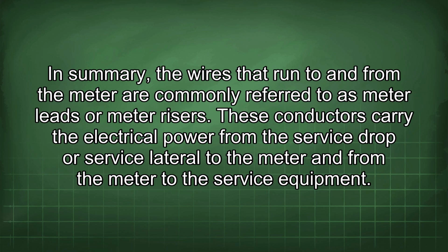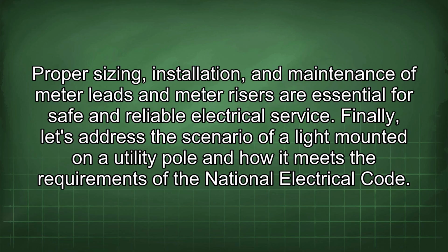In summary, the wires that run to and from the meter are commonly referred to as meter leads or meter risers. These conductors carry the electrical power from the service drop or service lateral to the meter and from the meter to the service equipment. Proper sizing, installation, and maintenance of meter leads and meter risers are essential for safe and reliable electrical service.